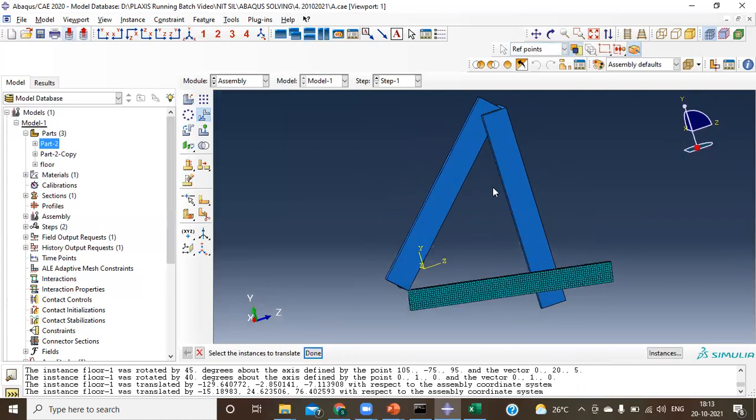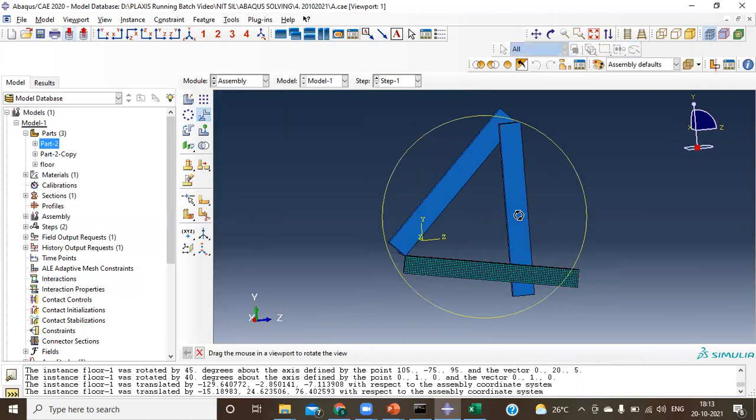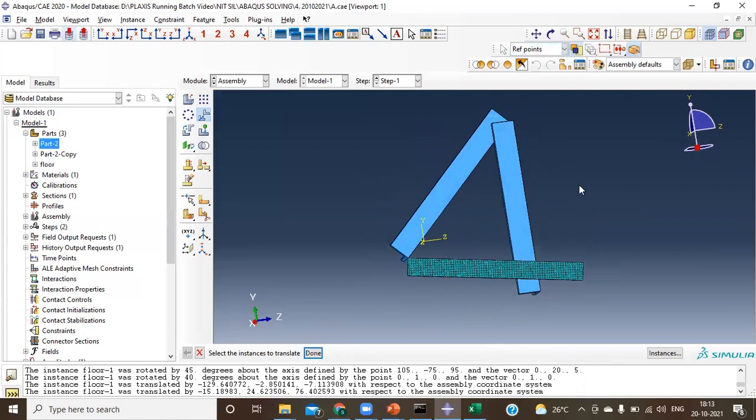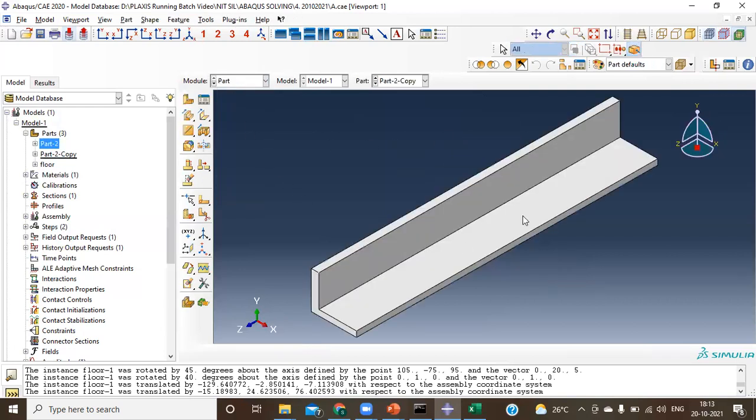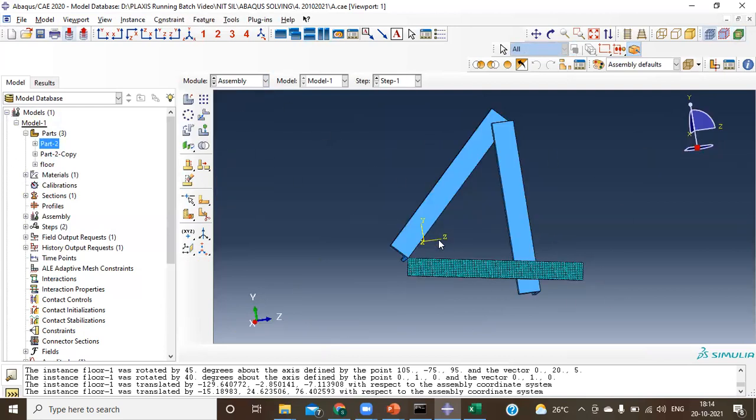Okay. So you have to play around with this too. There are other constraints also, like surface to surface constraints and all. That's why, when you go up with the cross section, I'll try to filter out many things over here itself. Once you call up the assembly directly, the part should come into its own position. That's what a good design should follow. You should not play around in an assembly module. Okay.